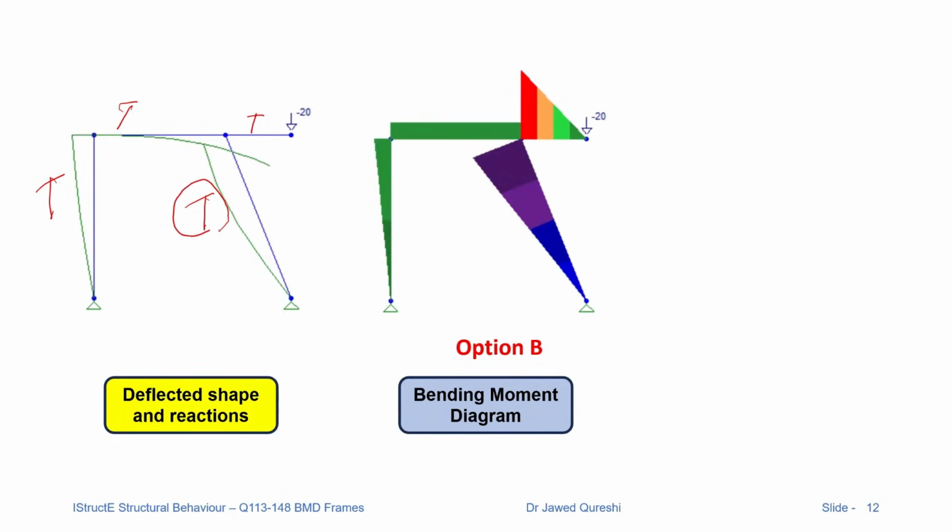As you can see, we have tension inside. We have tension outside, and the bending moment is not changing at all at this position. At this point, it is being divided into three parts. It's being distributed into three components, and the highest part is the overhang part, where you can see we have lots of bending. At this position, it is bending outwards.